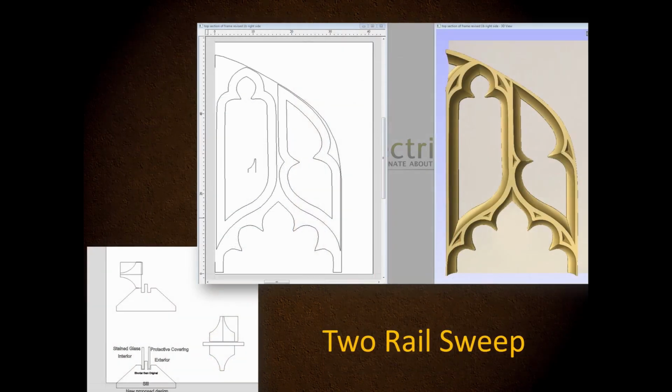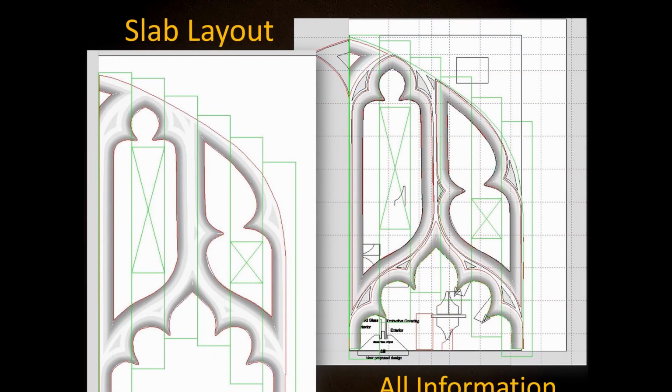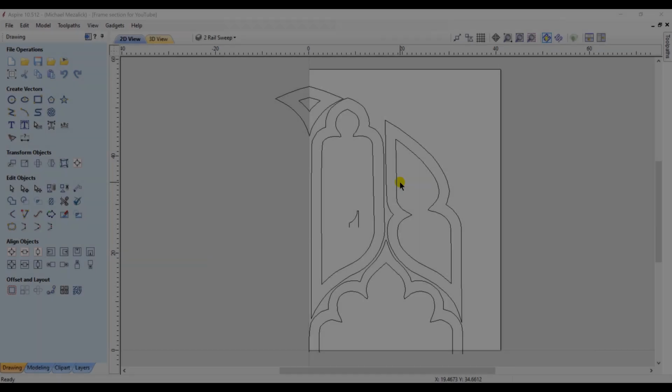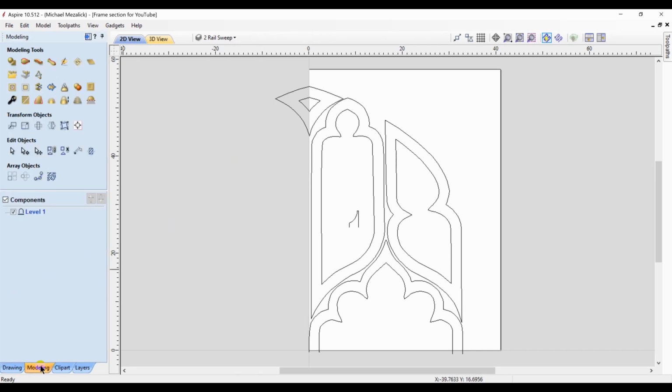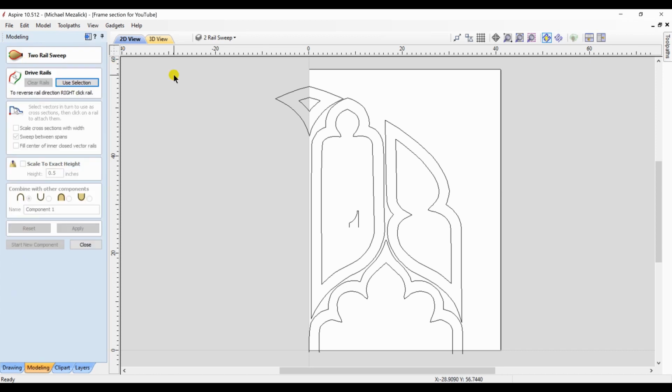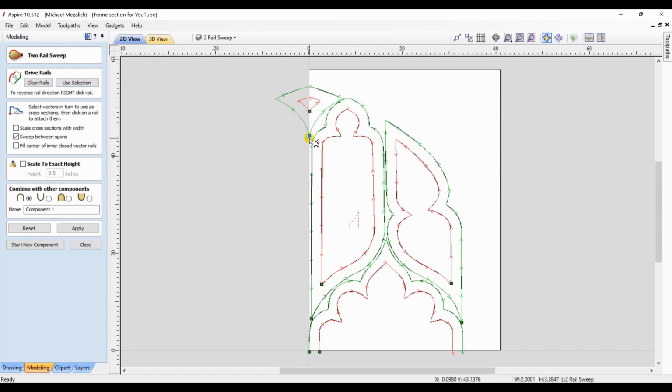The end product was a simple 2-rail sweep to be able to create the frame that we needed. I also blocked out in green the vectors for the wood to effectively use the lumber as needed. As with any 2-rail sweep process, we need 2 rails and a profile. Selecting one vector and then the other, choosing those as the rails. I then place the profile where need be.